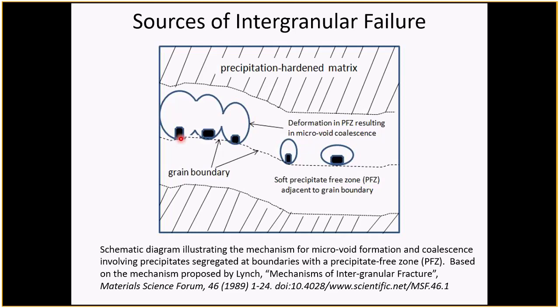But of course, what that does then is for a bog standard alloy operating at conventional temperatures, let's say you're deforming it to the point of failure, and what happens is that you're deforming the whole material, you're hardening it, you're elevating the stress that you're subjecting the material to, and eventually any material, just like you get in the neck region of a tensile specimen, will start to nucleate cavities.